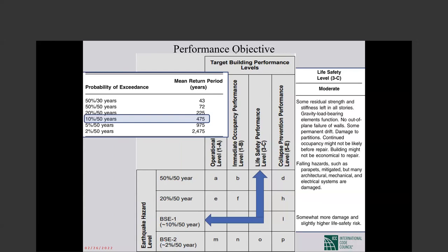For the nonlinear analysis, which hopefully we will discuss on Tuesday, the earthquake level becomes the target displacement. If they ask to check this building for a larger earthquake, it means push the building to a larger displacement.